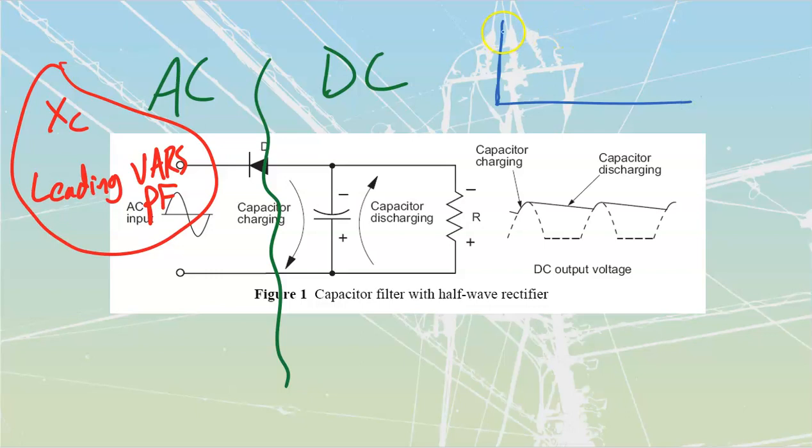So if I were to apply, this is my value of voltage that I'm going to have up here, and I've got no voltage, no voltage, no voltage, and then all of a sudden I turn on the circuit, close that switch, so that my voltage rises like that. What my cap is going to do is rise its value of voltage. It takes place over those 5 tau that we are going to have over there.